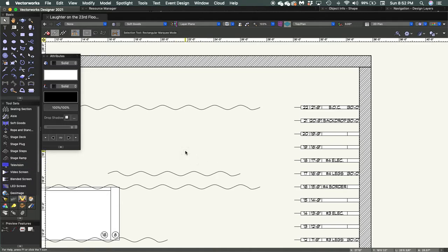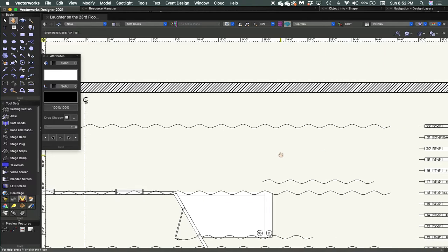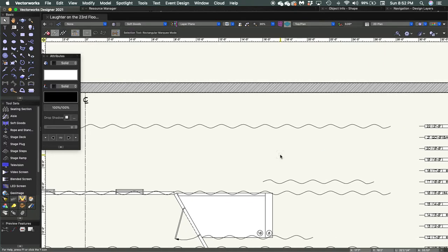We need to add one more piece of soft goods, and that's the backdrop that we're referencing on line set 21. We can do that in plan view by just representing a simple line with a 7 mil line weight. So I'm going to activate my line tool, make sure I'm in line with line set 21, come over to center.